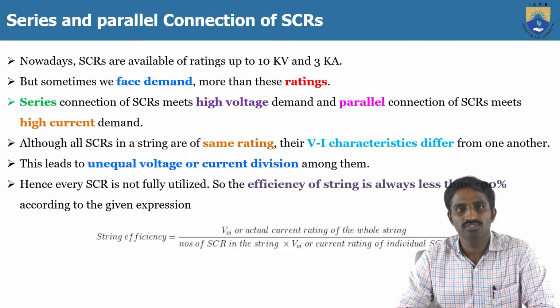So in those cases we go for the series and parallel connection of the SCRs. If any application needs a high voltage rating, we connect several SCRs in series.